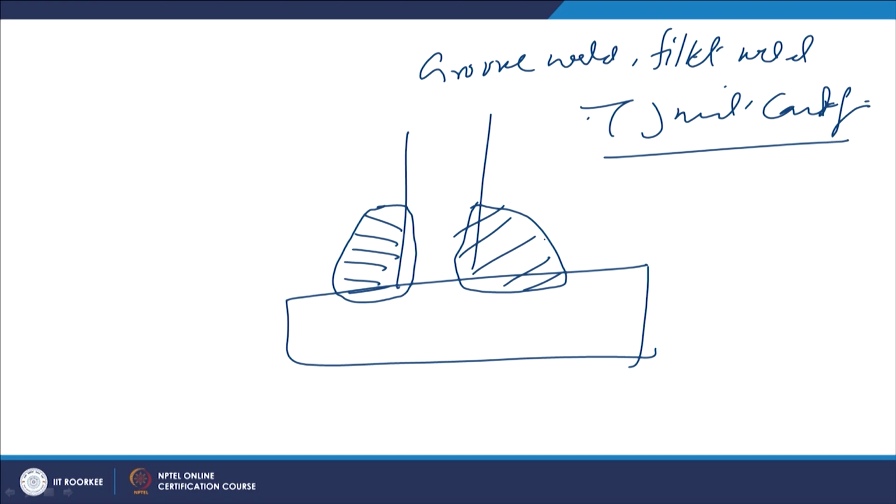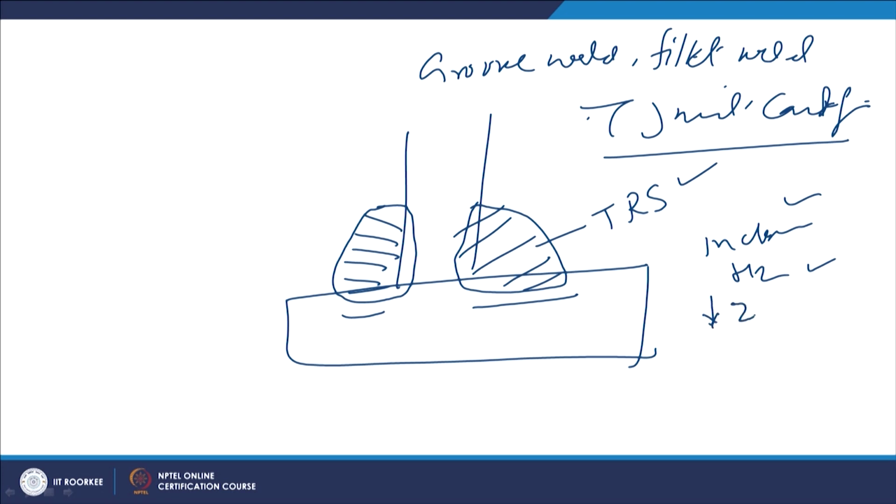Due to the shrinkage, the tensile residual stresses set up the metal next to the weld zone under very restrained conditions, and if there are inclusions as well as hydrogen, high tensile residual stresses, and limited Z direction ductility, it will easily promote cracks or lamellar tearing in the region next to the weld metal, and this kind of crack will subsequently propagate into the base metal.